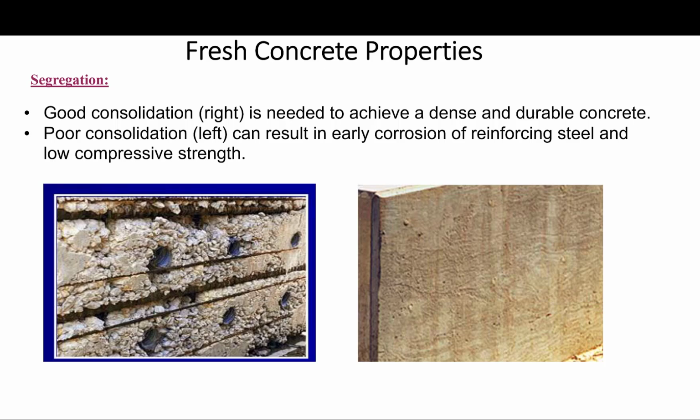And as I said, the benefits of a workable concrete mix cannot be overstated. Having a mix with the right workability will ensure that concrete is placed, compacted, and finished properly, which eventually contributes to the strength gain and durability of concrete. Learning what needs to be done to have a workable mix appropriate for a specific application will go a long way in improving concrete properties over time. Adding water on site to improve workability is not one of them, and this should be avoided at all costs.